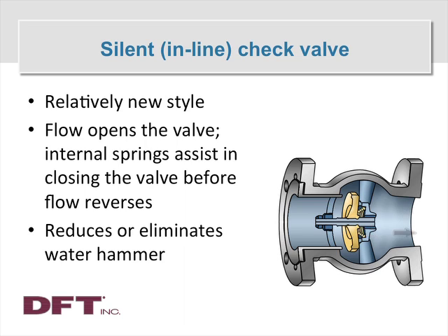Even exotic alloys and a variety of face-to-face standards also. The B16.10 standard, API 594, and MSS SP-126 are all different face-to-face standards that this style of valve is available in. The real significant advantage of this axial flow or nozzle style valve is that it allows modification of the opening travel to achieve a customized flow capacity. And we're going to get into why that's very important in a few slides.